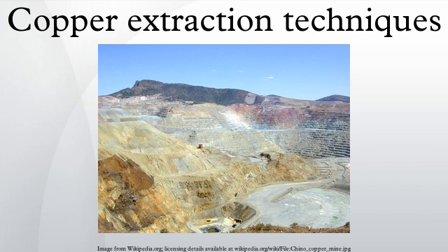However, the converter slag is high in magnetite, and some of this magnetite would precipitate from the converter slag, forming an accretion on the hearth of the reverberatory furnace and necessitating shutdowns of the furnace to remove the accretion. This accretion formation limits the quantity of converter slag that can be treated in a reverberatory furnace. While reverberatory furnaces had very low copper losses to slag, they are not very energy efficient, and the low concentrations of sulfur dioxide in their off-gases made its capture uneconomic.